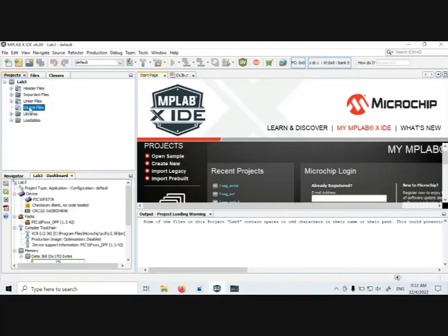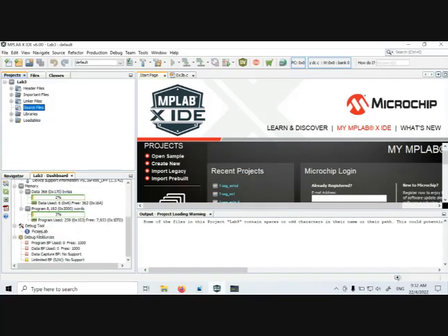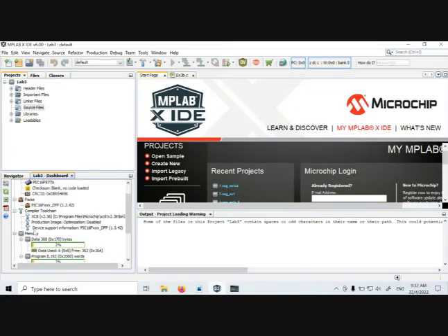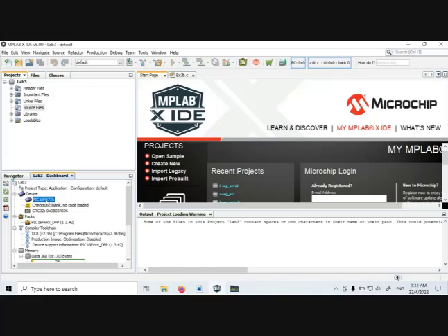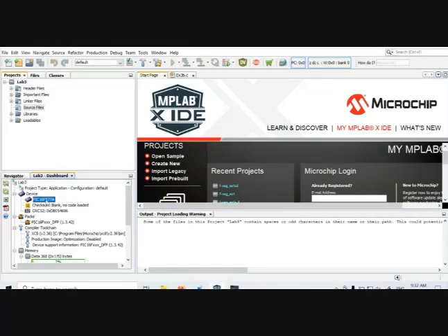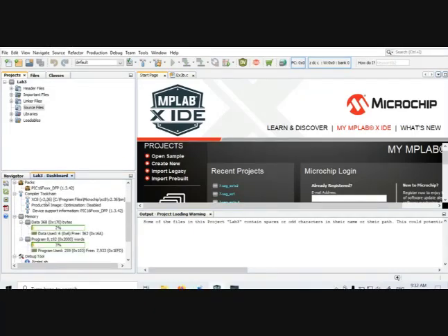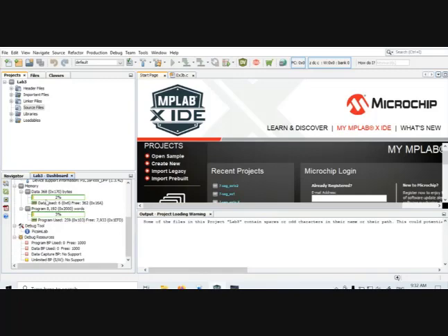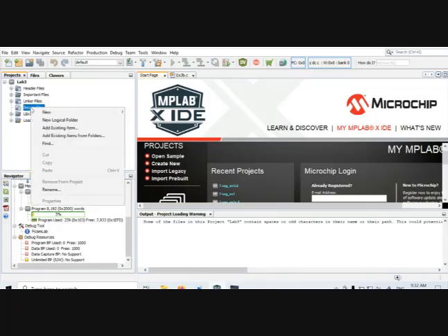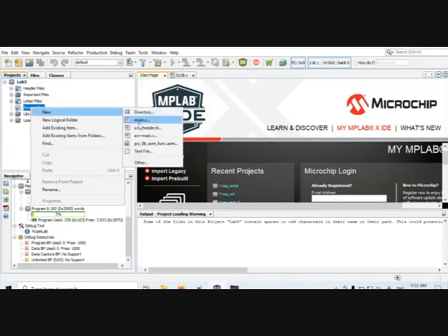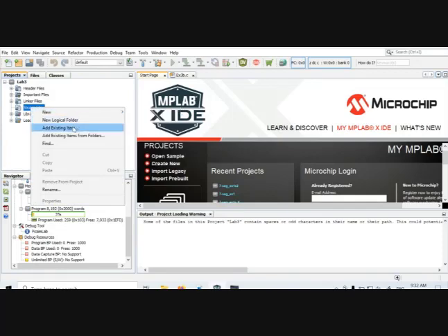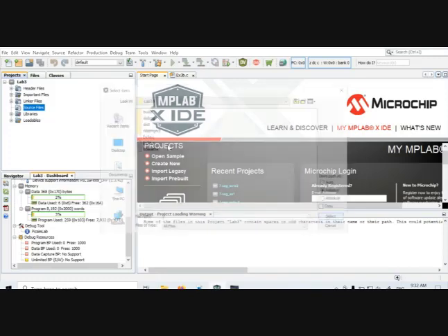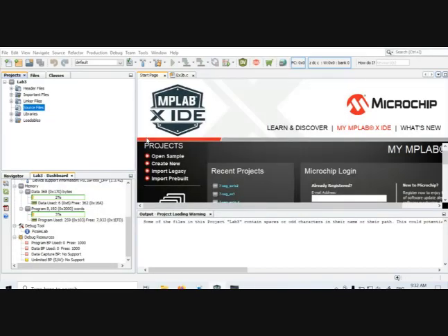Make sure that you create the correct program setting, project setting. Before you start, check first. The debug tool must be PicSimLab, the compiler must be XC8, and the microcontroller of choice must be PIC16F877A. You need to check this first. If everything is correct, you can start by creating main.c. For my example, I already created it, so I just add the program. So you can see here.